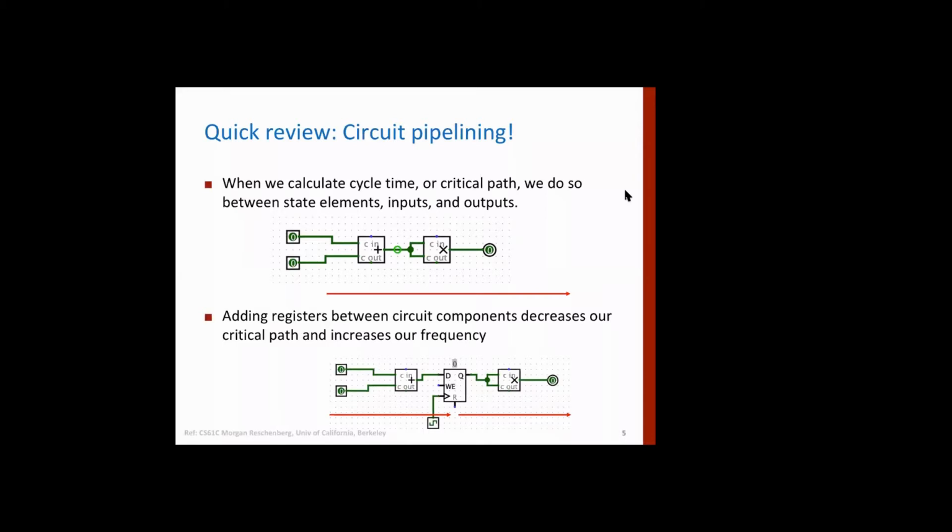The whole idea is that we can increase the clock speed by reducing the maximum delay to the extent that the work required to be done in that stage can be done in the clock cycle, right?